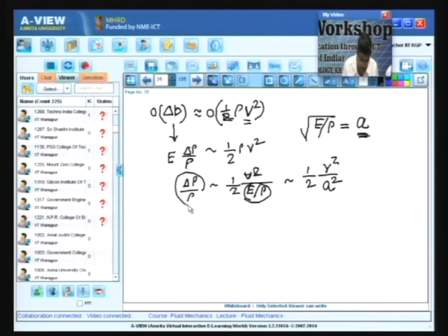Okay. So, therefore, we see that the change in density divided by the density, the relative change in density in a flow, is related to its pressure through its characteristic velocity because of Bernoulli's theorem. Since the pressure drop is of the order of dynamic head, almost equal to half of the square of the characteristic velocity of the flow medium divided by the square of the acoustic speed in that medium, and this depends upon the state of the medium, which is designated by its bulk modulus of elasticity and rho by this equation of Laplace.